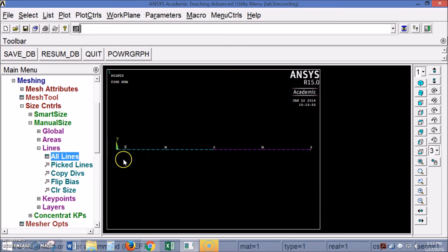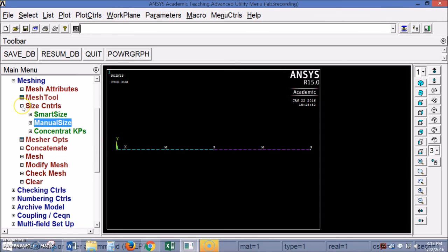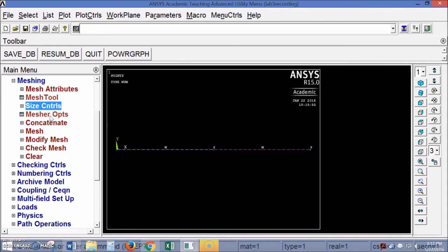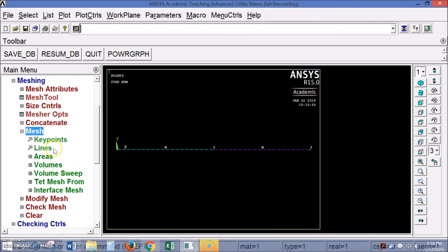And now, if you remember earlier, for each cross section, we specified an x and a z, we specified 2 dimensions of how it was going to divide up those elements. We specified how many in one direction, how many in another. And now we've given it a 3rd dimension of how to divide up the elements. So when we apply our cross section, it'll have a 3D mesh of elements going through our whole model. So if something's not meshing correctly, you have to think whether or not you've applied specific sizes to your elements in all 3 directions. So 2 directions on your cross section and a 3rd direction when you extrude it along the line.